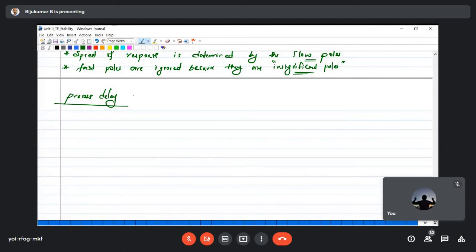We can also call it time delay. Time delay in the sense that sometimes from one component to another component, there will be some processing delay in practical cases. Suppose the delay time is delta, the corresponding transfer function of that delay is e power minus delta s. So if you have a system function e power minus 2s, it means that the delay time is 2 seconds. This also you keep in mind.